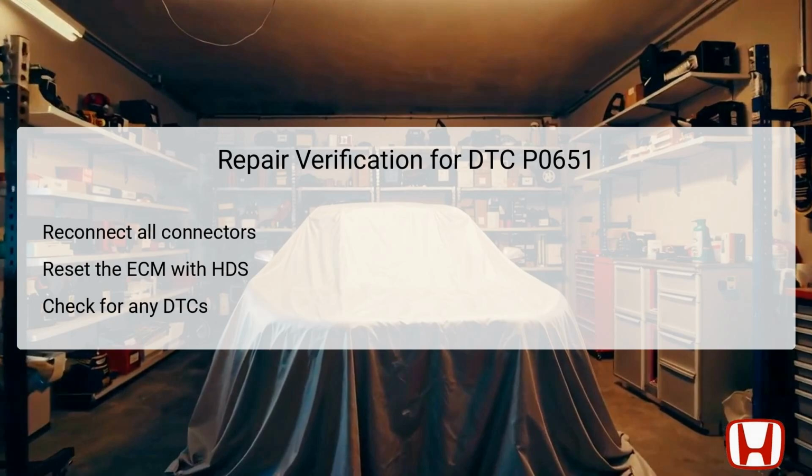The next step is to reset the ECM using the HDS, which reinitializes the onboard diagnostics and clears any stored codes. Following this reset, you should perform a check for any pending or confirmed DTCs using the HDS again. If DTC P0651 reappears, this indicates that the problem persists, and you should revisit the previous troubleshooting steps to identify any remaining issues. If no codes appear, it confirms the repairs have been successful, allowing the vehicle to operate without error.